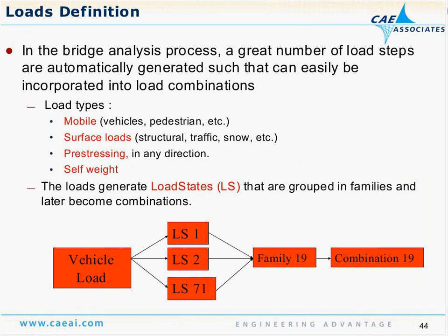Moving on to loads. So for the loading environment to load our bridge, the loading capabilities use ANSYS direct commands in terms of putting on pressures, accelerations, forces, moments, but a lot of these have been automated. So the CivilFEM capabilities will automatically generate, for instance, surface effect elements to prescribe a mobile load on your bridge deck. It'll take those and prescribe the appropriate scaling factors for those loads